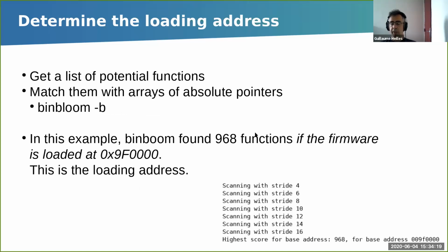Here are the results. On this firmware, binbloom has been able to find a correlation on 968 functions based on the assumption that the firmware was loaded at this specific address, 9F0000. So it's a pretty high number of functions, it cannot be by chance, and it means this is the loading address. And if you use this address in IDA, everything will just match.